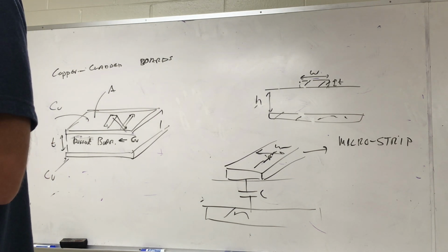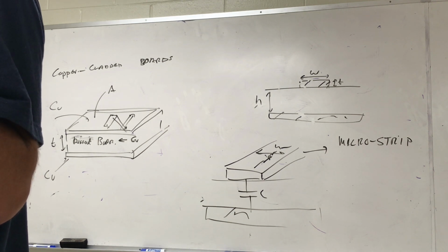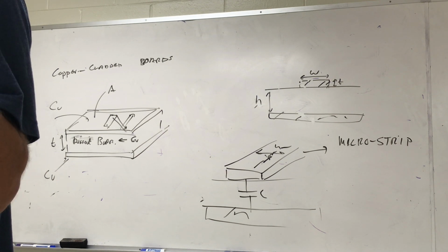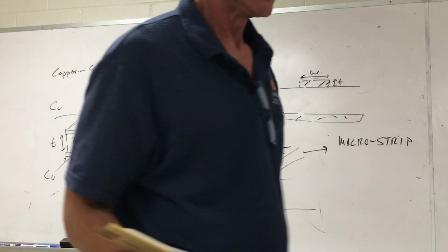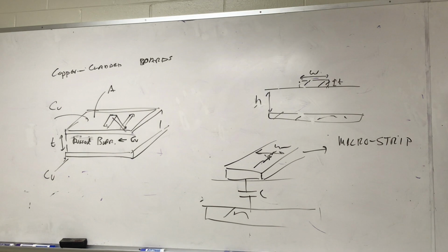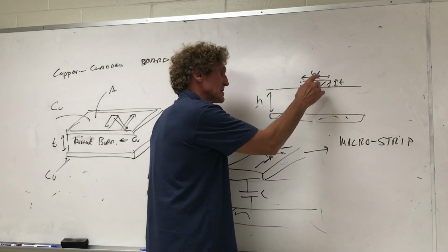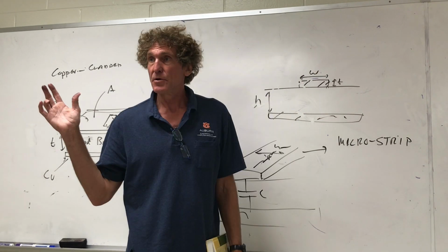When you actually want this information, all the formulas he has in here are approximations, and there are exact tools online that you can use. In my experience, if you have a controlled impedance line, you let the manufacturer know, and they'll adjust it to whatever is needed. But I should say this: if we have a certain thickness board, H, and we want the characteristic impedance of this line to be a certain value, it's based only on the width. You can adjust the width.